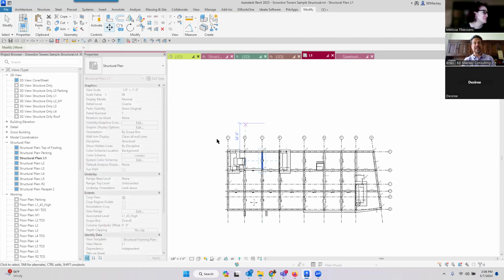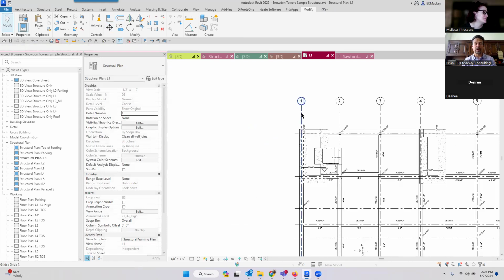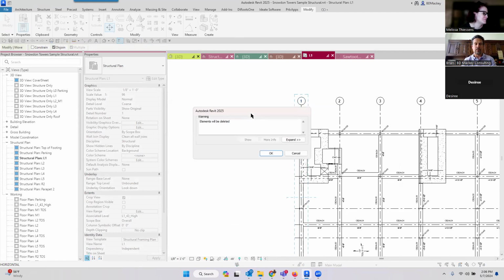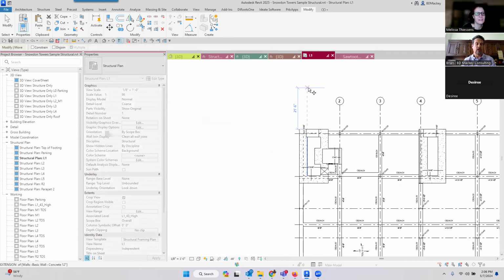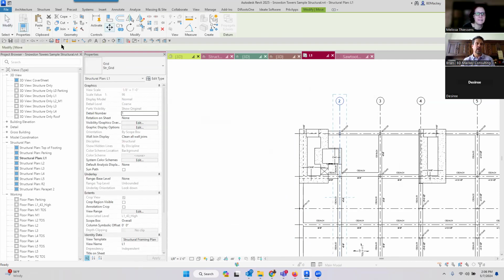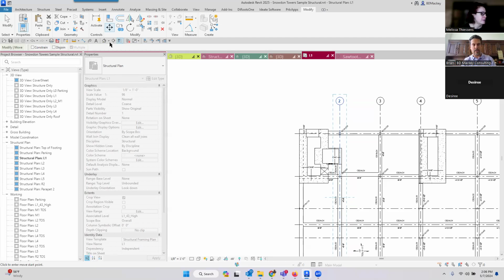Yeah, so if I need to use the disjoin tool, I will literally be like, okay, I need to move this with disjoin. Let me check disjoin. Let me move it. And then I will literally go right back into the move command and uncheck disjoin and be like, cool, now I can cancel. Because if you don't uncheck disjoin, it remembers that setting. So when I need to use it, it's a rare occasion, but I just go right back into the move command to toggle that back off. That is a good tip.